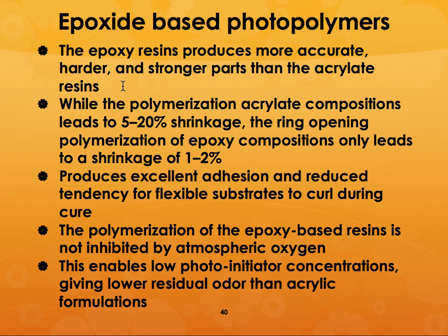You're going to have some amount of shrinkage, and that shrinkage can vary from 5 to 20%. But that shrinkage also gives you excellent adhesion and reduced tendency for those flexible substrates to curl during the cure.